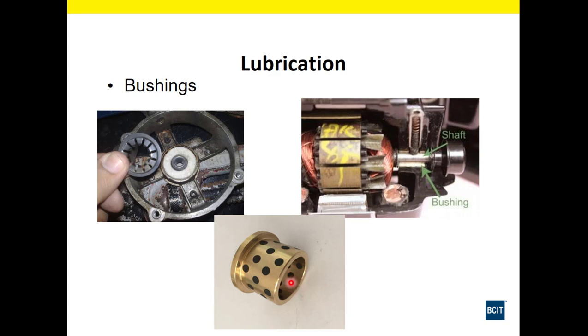As the bushing wears or heats up, the lubricant melts and then lubricates it, and it keeps itself at a nice operating level. On this side we see a grease slug or cartridge that, as the motor shaft turns, and here's the bushing, and this has been cut away intentionally, as the motor shaft turns, it's going to wear or create friction on this grease slug here, and it's going to lubricate over time the shaft and the bushing.